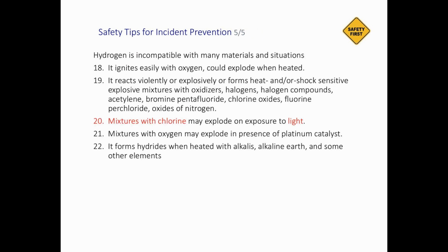Hydrogen is incompatible with many materials and situations. It ignites easily with oxygen. It reacts violently or explosively, or forms a heat and shock-sensitive explosive mixture with oxygen. A mixture with chlorine may explode on exposure to light. A mixture with oxygen may explode in the presence of a platinum catalyst. It forms hydrides when heated with alkalis or alkaline earth metals and some other elements.